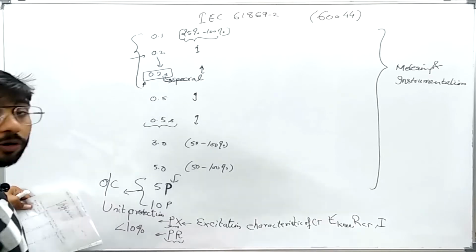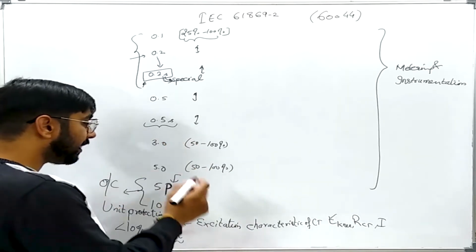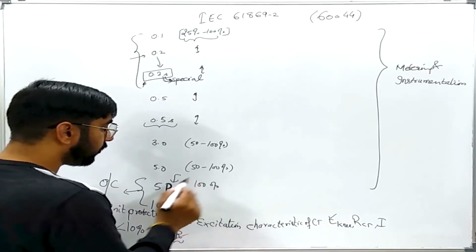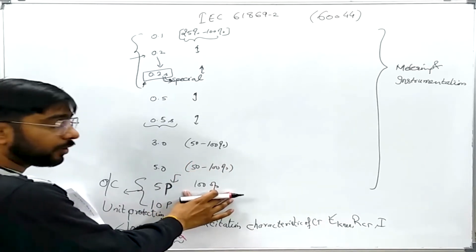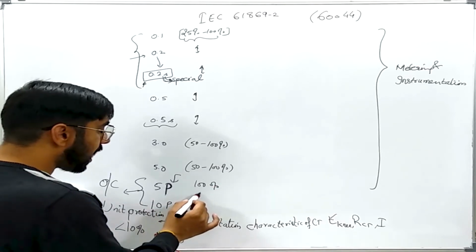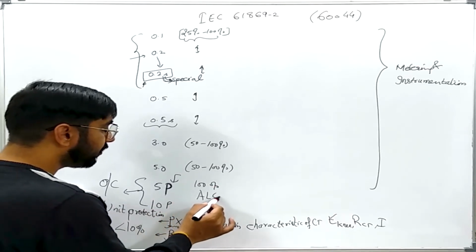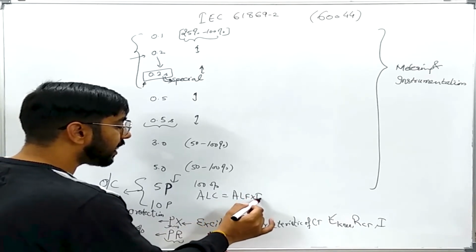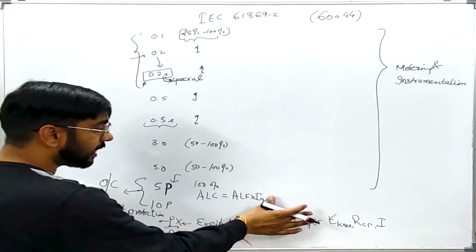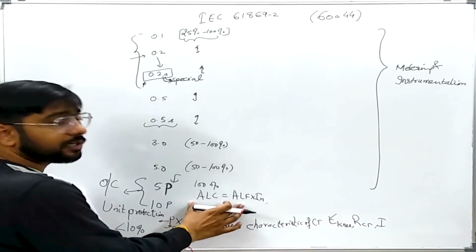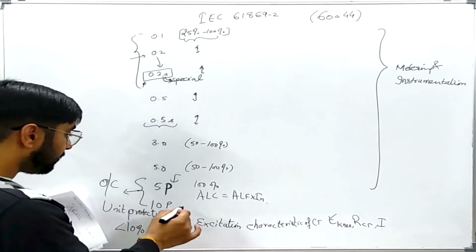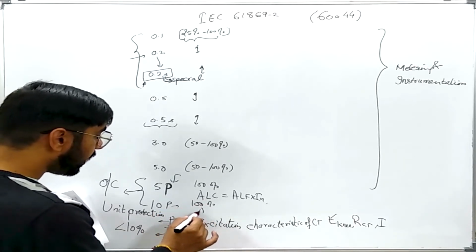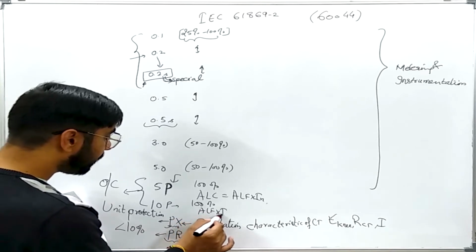Now all the protection class CTs will give good results over 100% of the rated VA connected to them, up to the accuracy limiting current, which is equal to the accuracy limiting factor times the nominal current, or the rated current. These two terms we have seen in our previous lecture. Similarly, this will give good results from 100% to ALF times IN.